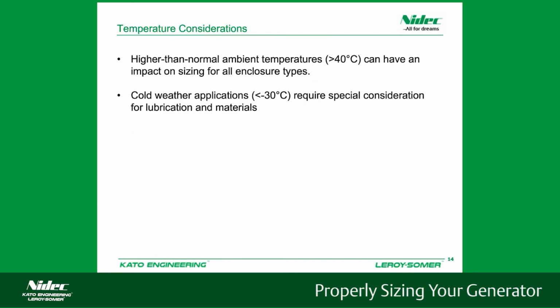So again, we see here a higher than normal ambient, greater than 40 degrees C will have an impact on the sizing for all enclosures. And cold weather applications down to minus 30 degrees C and below will require special consideration for lubrication and materials. So that's going to typically cost a little bit more. It's not going to require an increase in size of the generator, but it will have specialty materials.